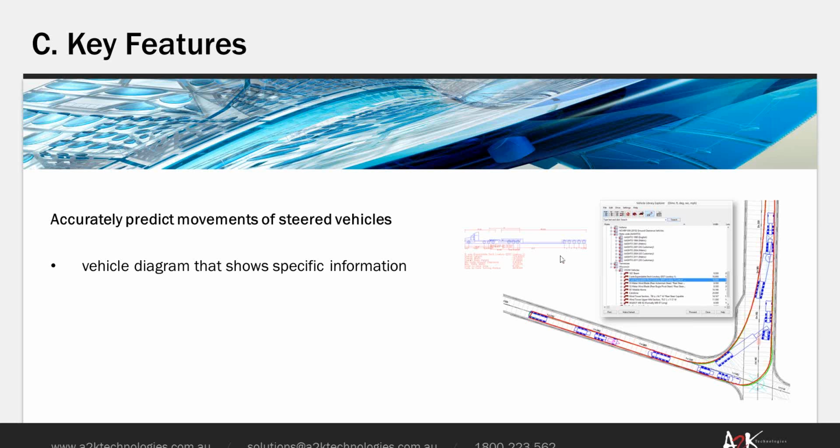When you select a vehicle, you can also place a graphic in the program so you can actually see what the dimensions of the vehicle are at any time. So clearances, wheelbase, width, height, those sorts of things. Once you start drawing your vehicle track in the horizontal space, you can see exactly where the vehicle goes, the extent of the vehicle, the wall-to-wall or curb-to-curb settings, so you know exactly what your envelope is.